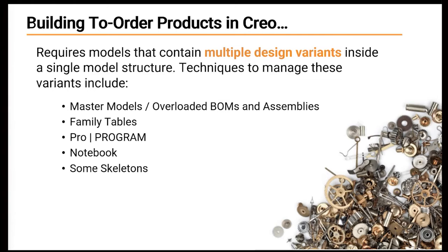If you think about it, I can take every single part that could ever be in this assembly, in whatever location it's going to be, pre-build it ahead of time, and then throughout the year use a family table, program, notebook, or model builder. All of them are based on this core idea: I have a large assembly, I want to overbuild everything in it and suppress what I don't need.